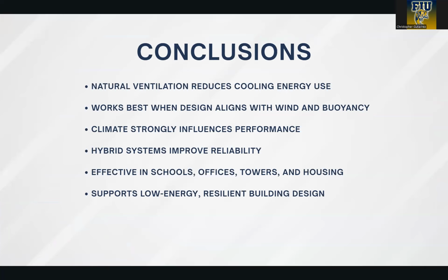Okay, and now conclusions. Natural ventilation reduces cooling energy use when design and climate align. It works through wind and buoyancy, like we spoke about earlier. And climate has a major influence on performance. Hybrid systems improve reliability when natural forces are weak. Real projects show strong results in schools, offices, towers, and housing. Natural ventilation remains a practical, low energy option when applied carefully.